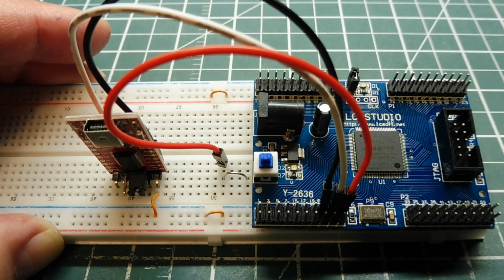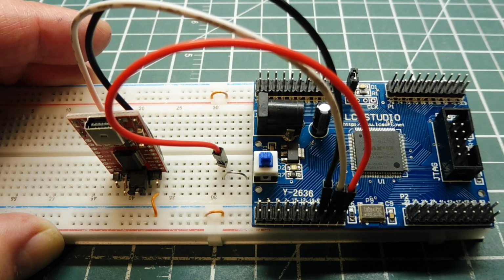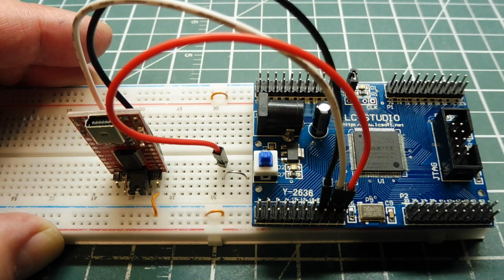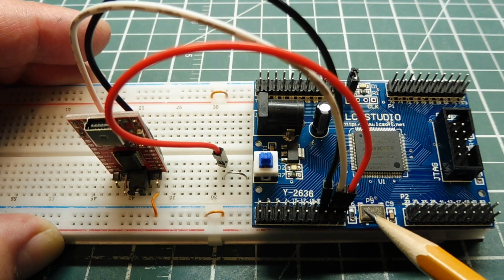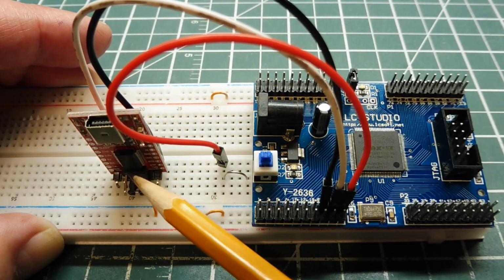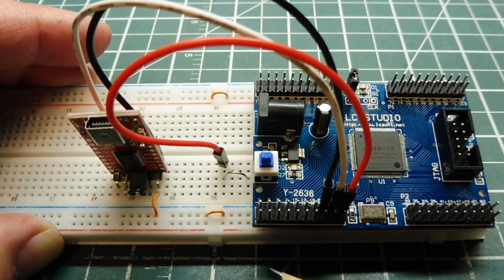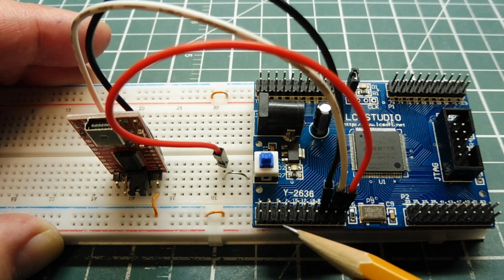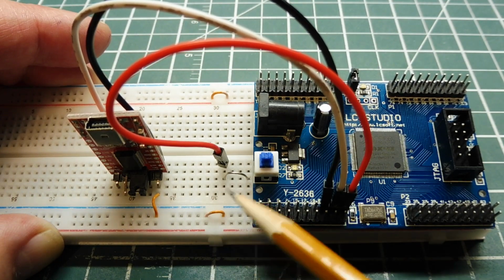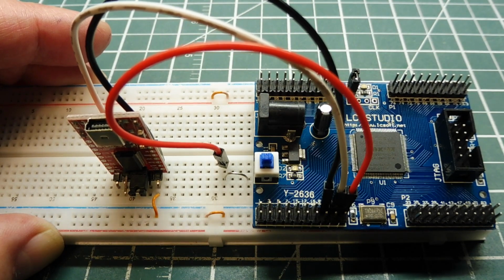We are going to build an FSK generator using a CPLD. Now all the logical functions needed are available on the CPLD, and it has an onboard 50 MHz crystal, so we could use that as our clock. And I have an FTDI module, a USB to serial, connected up to the CPLD, and that will input our data. So I could actually send a text file into the FSK generator and we can monitor the output. So next we'll have a look at the schematic inside the CPLD of this FSK generator.